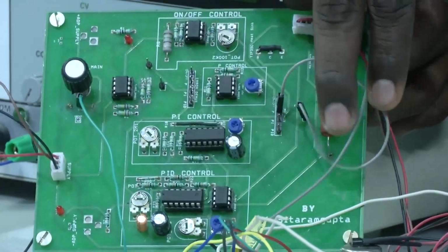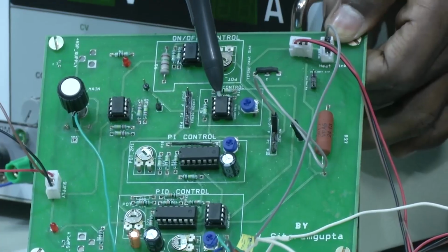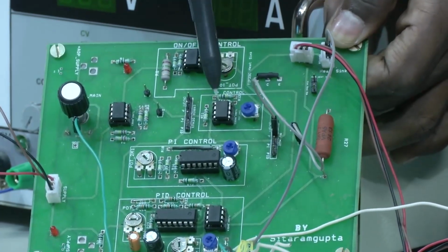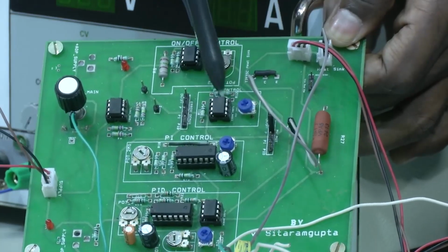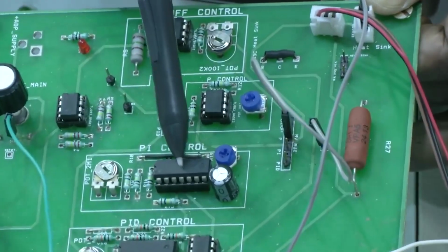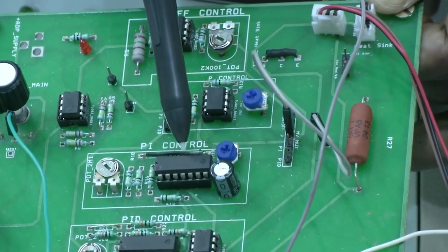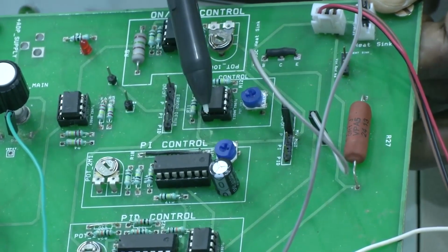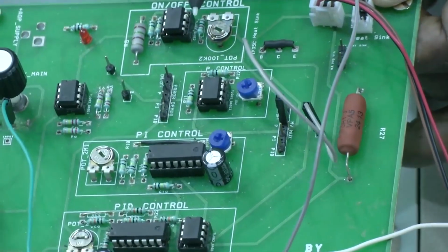So, we do have a P controller. This P controller is also implemented using a TL082, so it has both op amps. The signal conditioning and P controller that we have seen is completely implemented using this. The other one is TL084, which has 4 op amps, and we are using only 3 op amps, right. The gain is completely set by using the feedback resistor, or we can go with the initial P gain.